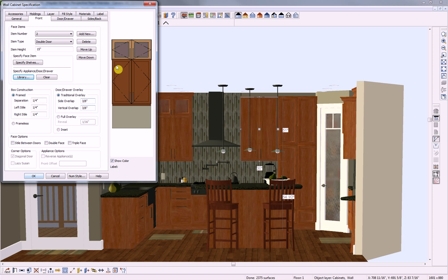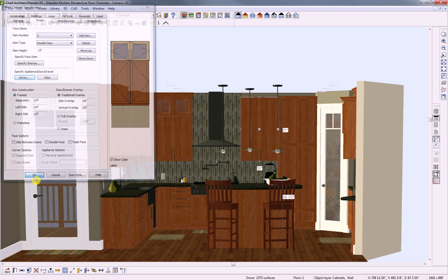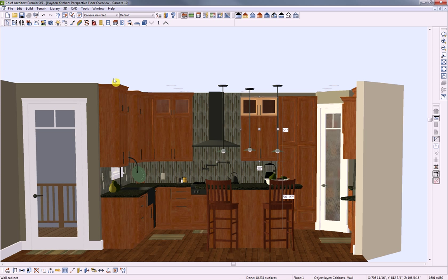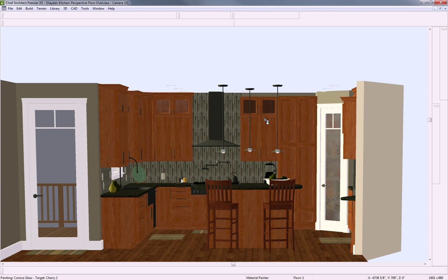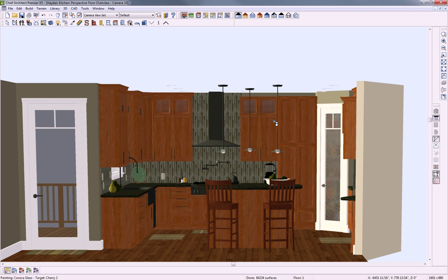And then we see there's a material mismatch, but we all know how we can quickly change that. Go to our eyedropper tool, pull up this material, and just add it to our door. And then our glass is a bit of a mismatch, so let's pull up this glass and add it over here. So that's how we can handle multiple door styles on a single cabinet.